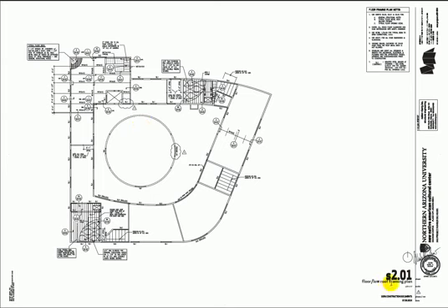You can see this says framing plan. So framing indicates that it's structural. So I might concentrate a lot down here on the titles of the pages. You can see right below here that these were issued for 100% construction documents, so I expect them to be complete. This has floor and low roof, so I'm looking at this saying, okay, some of these spaces here look like they're open, and some of them look like they might be floors, and some might be roofs. So I'm not quite sure what's going on.